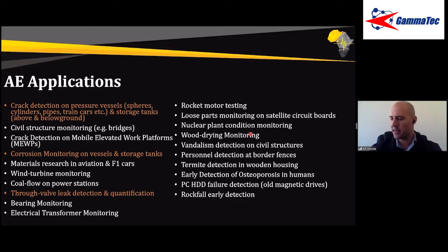So if you have a particularly strange setup of a pipeline, so various loops, etc., and you don't particularly need exact, precise to the millimeter location, you just want a general location, you would then attach sensors to the entire line, maybe a bit more to more complex geometry, and you can get a general area which then you can focus with your follow-up NDT applications on.